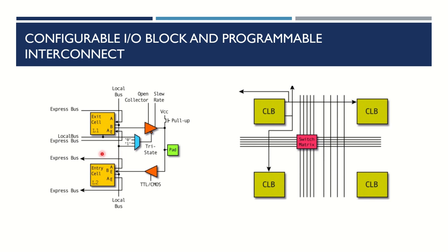The slew rate of the output buffer can be controlled to minimize transients on the power bus when non-critical signals are switched. The registers available in the input output path of an IOB are driven by separate invertible clocks.